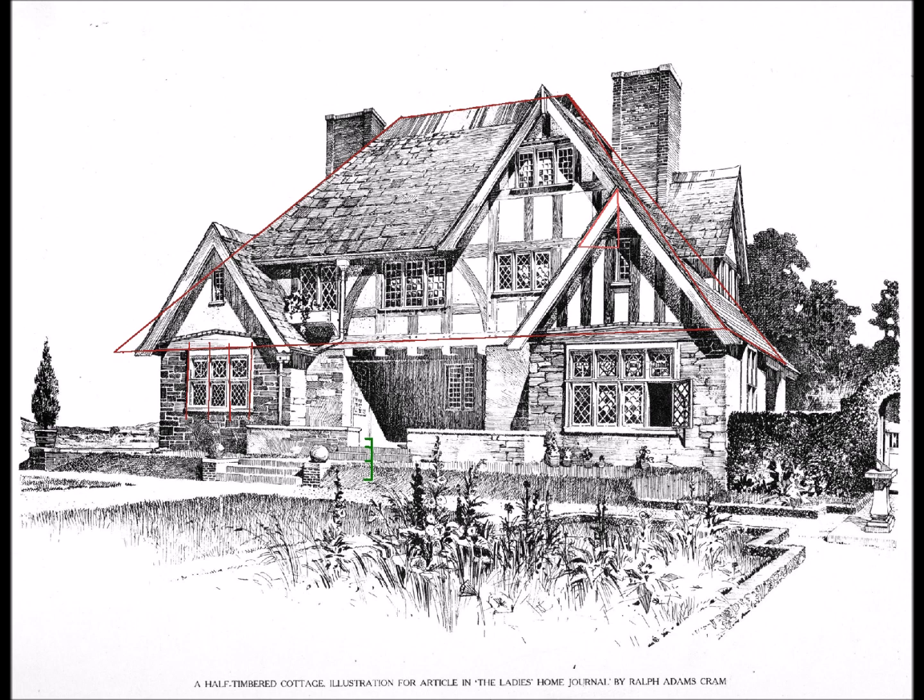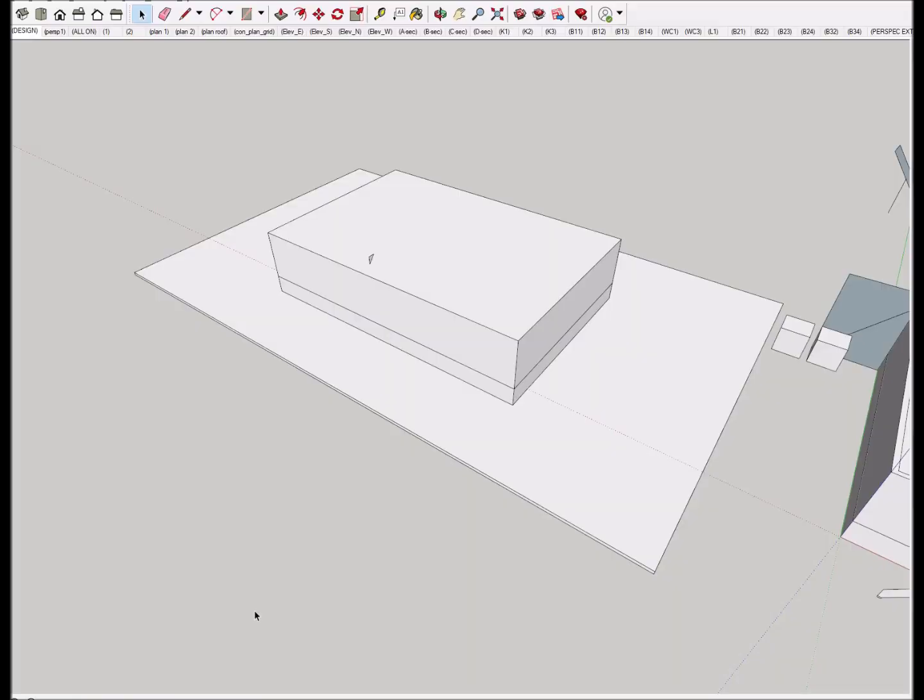And then we've got a windowsill, top of the window, some beams up here. In the porch we see a door, faintly outline of a door. We can see there's not a lot of space above the door to the ceiling of the porch. So I'm assuming this house has an 8-foot ceiling on the ground floor, based on that door and based on the window. So in the model, I've used what is standard construction height in the United States now, 8 foot 1 1/8 inches. And that's just a number that comes from what is standard carpentry practice these days for an 8-foot ceiling. So although I'm calling it an 8-foot ceiling, it's actually 8 foot 1 1/8.